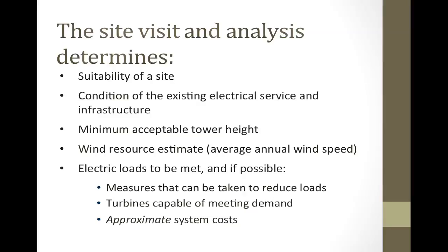So we have to discuss what the loads are going to be that are met. Specifically, what does the customer have plugged in? What are we trying to do? What are their goals? Do they want to go off grid? If they do, there's a lot of extra things that would need to be done on a site assessment. If they do not want to be off grid, but are interested in connecting to the grid and perhaps storing some of their energy on the grid for when they're not using much energy but the wind is really blowing. So we have to take a look at what those loads are, which means visiting the property, walking around inside the home, getting the customer to tell us exactly what equipment they have.